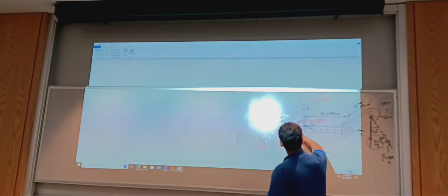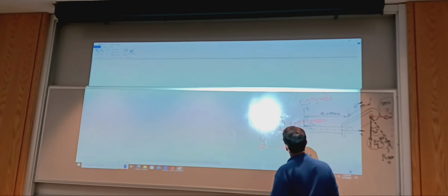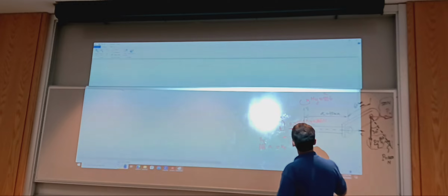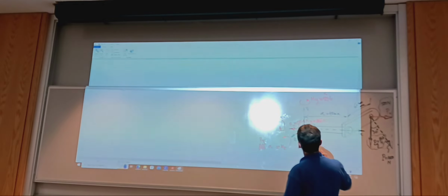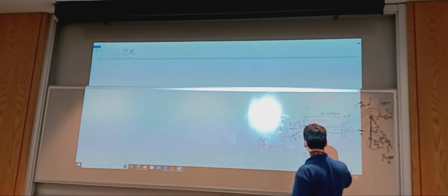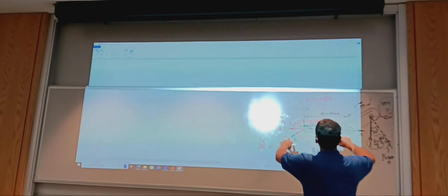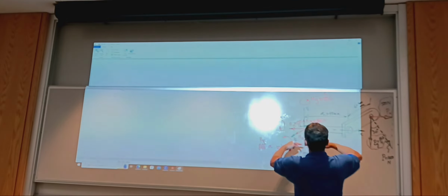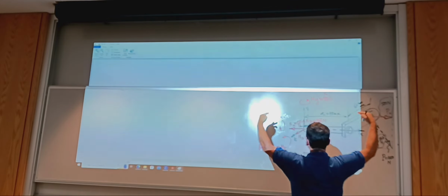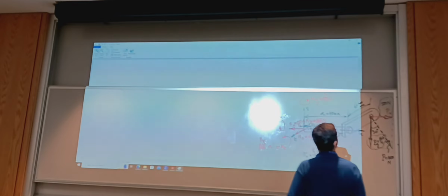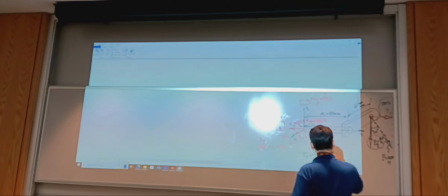Because of Px, it's going to be primarily bending. So it's going to be the same, or Py times a, that's the moment, over S of the solid round. And because tension is on top, compression below, to that tension on top I'm adding the force, and it's Px over area of the solid bar.